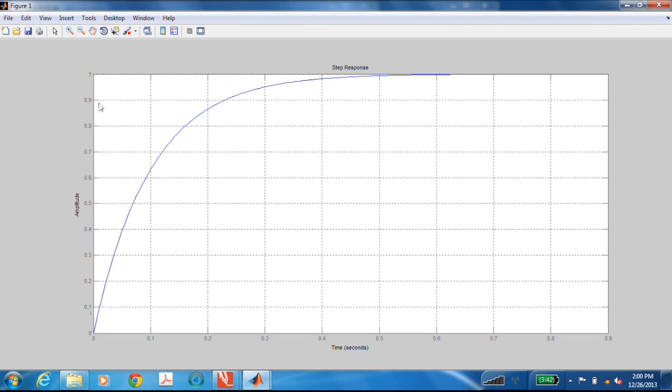So we gave it a step input of 1. And the response of the system has this exponential rise, like so, up to 1. At time equal infinity in steady state when nothing is changing, notice that V0, the output, which is what we're looking at here in blue, is equal to the input, which was equal to 1. So again, we have confirmation of our V0 equals Vs.